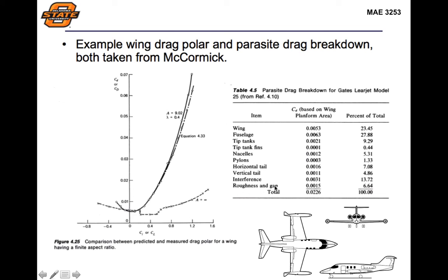We haven't talked about the gap and roughness effects. That's due to the fact that when you're manufacturing the aircraft, you will have different pieces as you overlap your structure together and your skin, gap effects that add additional drag as well.